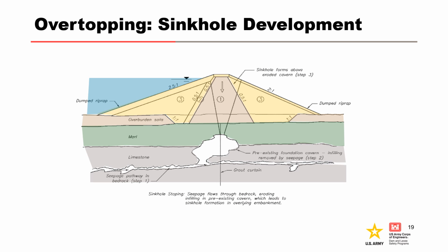Where the sinkhole develops is critical along with the water level at the time of occurrence. In this first example, a sinkhole at the crest is large enough to lower the crest, leading to overtopping. If the sinkhole develops at the downstream toe, it must lead to progressive slope instability and eventually overtopping. The event tree may need to consider the sinkhole location, if not well defined by the site characterization, and understanding of the foundation geology. For conduits, pipes, or culverts, the location could be informed by video inspection results.